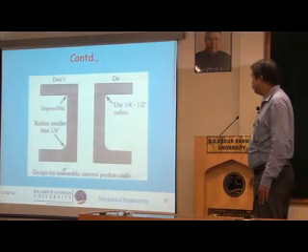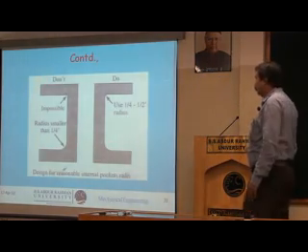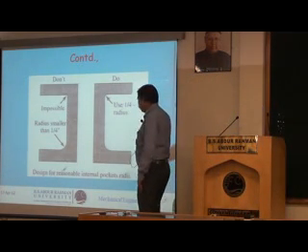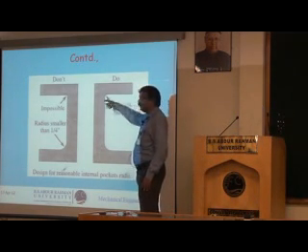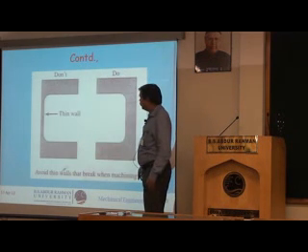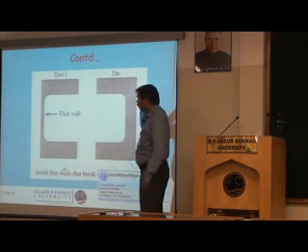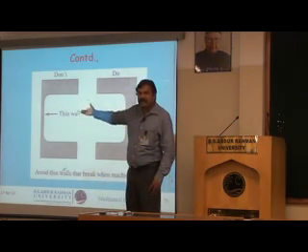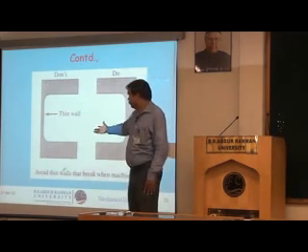Next slide please. So, don't provide a very small radius here, it is impossible to machine it. Next. Don't provide too thin a wall. If you provide a very thin wall, the cutting forces itself might break that wall. Next.